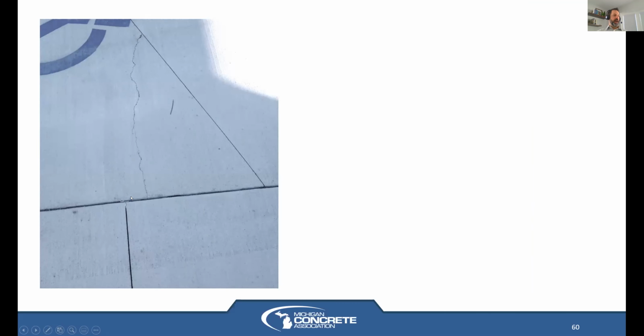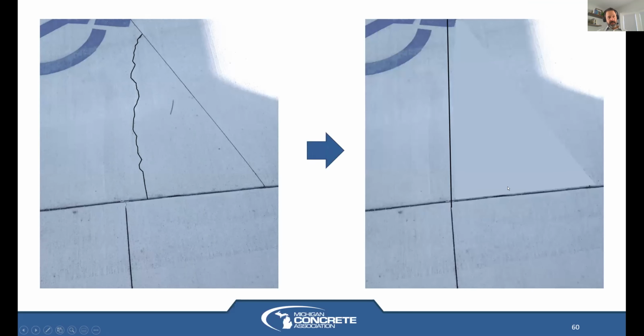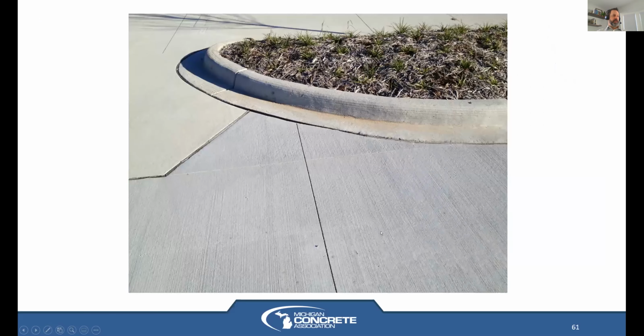All saw cuts should line up. So, just redrawing that, what should have happened is something like this. We stop that cut back there and dogleg it, which just means we change its direction. And the operator stops, picks up the saw, remaneuvers it, drops the blade, and continues on in line with this other cut. That's what we would rather have seen.